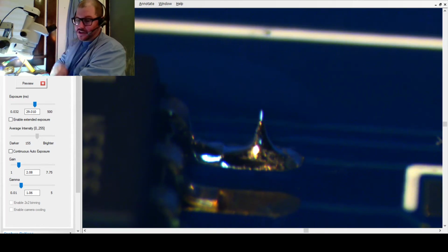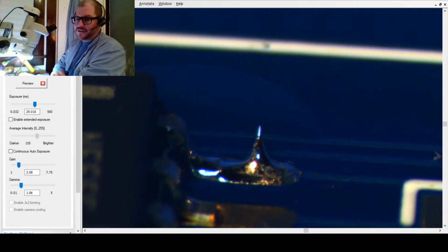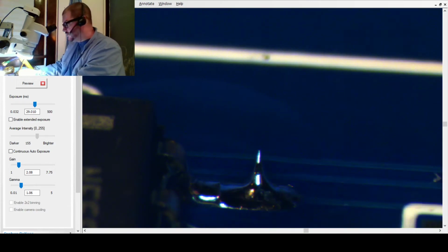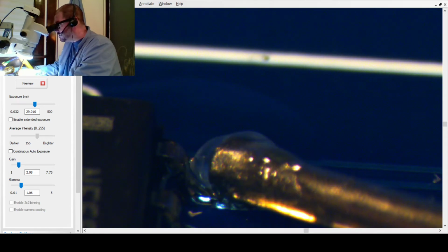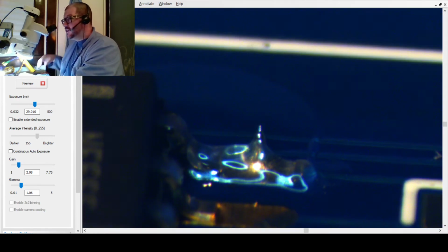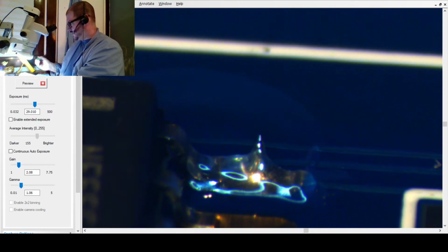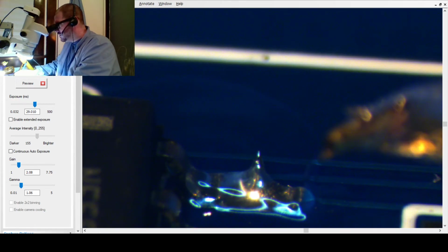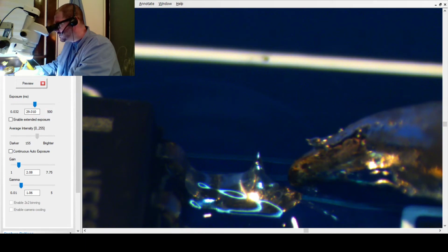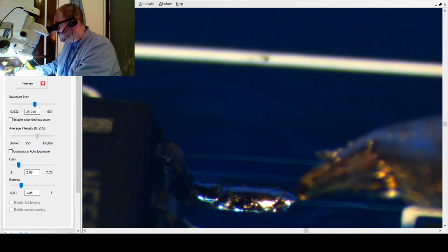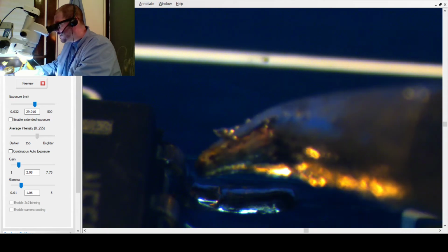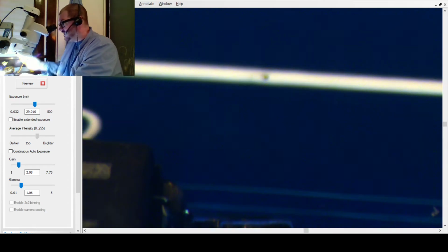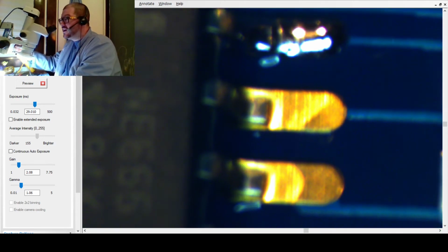But under the conditions that the solder is in and the temperature of your iron, this can actually happen. The way that you get rid of this is you first apply a little bit of some fluxing agent to this here. I'll try to do this at an angle. Then you take your soldering iron, waiting for it, of course, to get up to its temperature, and then hit the fluxing agent and watch as that solder just falls back down and tries to form back over to the nearest solderable surface, which is kind of a neat thing the way it does that.